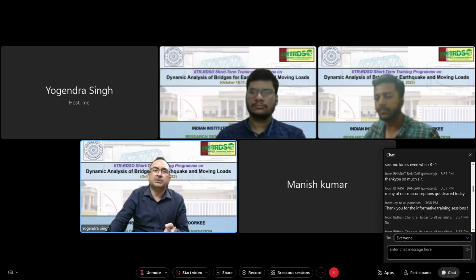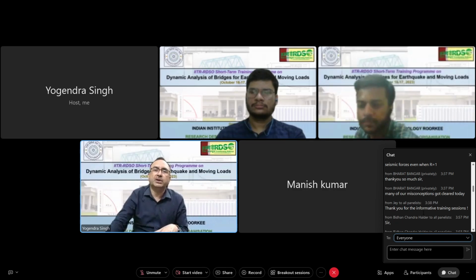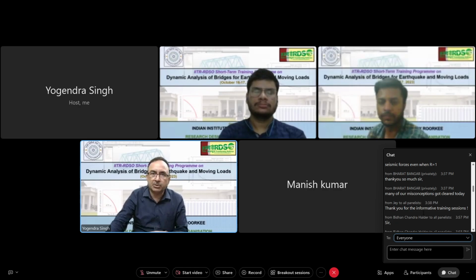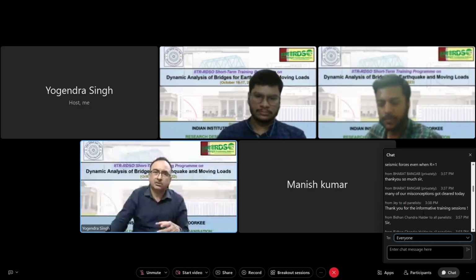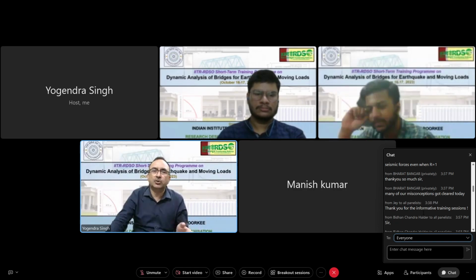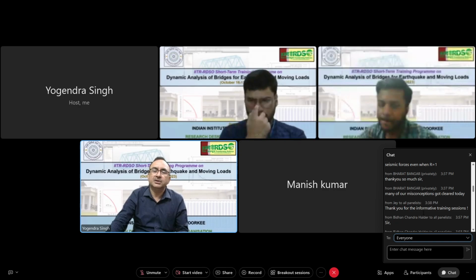If we are taking two components of the ground motion and scaling them, we have to be clear about how your target response spectrum has been obtained, whether it is obtained by SRSS, or it is the maximum component response spectrum, or it is RotD100 or RotD50. The same processing you should do on your recorded ground motion as was used for your target response spectrum. If somebody is using the response spectrum of an American code for an American site, then the process will be different. In the Indian code, it is just the maximum ordinate out of the two. Whichever is the maximum recorded component, that has been considered.